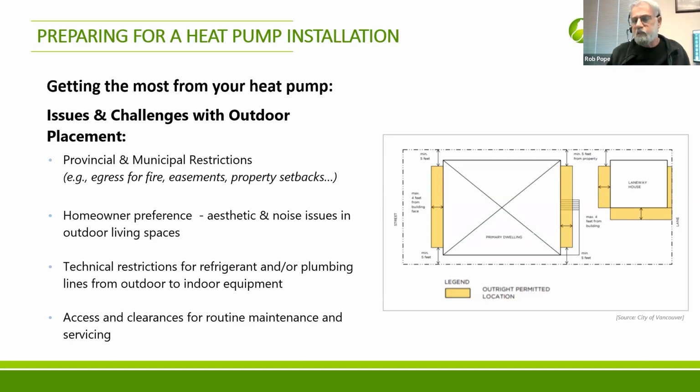So they don't just give you those components, they give you what your efficiency drops are, because when you have that situation, you're above the maximum. You don't just have that issue with the oil potentially separating from the refrigerant, but you also have an efficiency drop, a capacity drop. So it works out that you don't want to go outside of the limits of the line set length. More or less, that's the easiest thing to do, is stay within the max. And different manufacturers have different maxes. You take, for example, a Mitsubishi or Daikin, and you can go 160 feet, right? So it depends on the equipment as well.